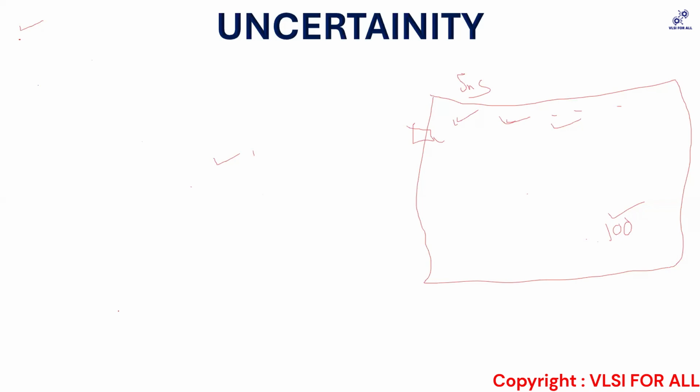Okay. So similarly, it happens in the real world that PLLs are also machines, right? They also have a margin of error. Because of that, it can happen that the clock which is expected to arrive, let's say, every 10 ns, keeps coming, but it is possible that sometimes I might get the clock at 10.2 ns. It is possible that I might get the clock at 9.8 nanoseconds, right?